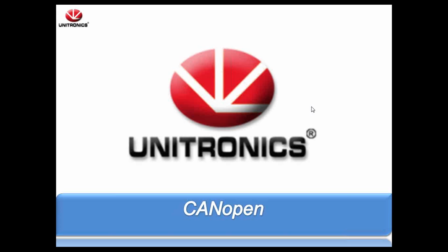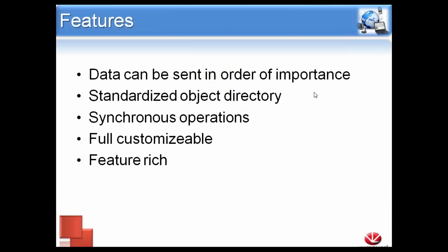Today we're going to be talking about CANOpen, one of our CAN bus protocols for communicating with CANOpen devices. CANOpen is definitely a very feature-rich protocol. It has a lot of bells and whistles, so to speak, that you don't see with normal protocols. One key feature is the data can be sent in order of importance. So we can give the most important data, for example, maybe an alarm or an error message, a higher priority, and it will always be sent before any other messages. By the same token, we can also give a message an extremely low priority, and it will always be sent last.